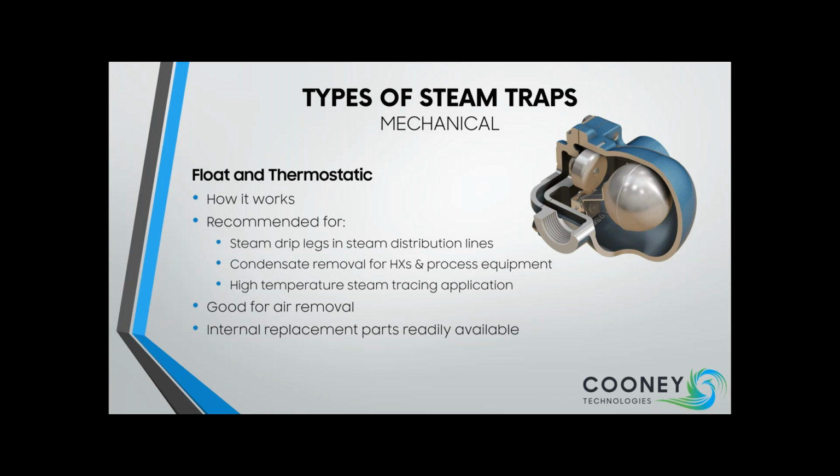We have the F&T trap, or the floating thermostatic, that has an internal mechanical hinge float device you can see in the cutaway here. When collected trapped condensate raises the float ball, which in turn opens the discharge port, the steam system pressure forces the condensate out through the discharge port. When the condensate level drops, the ball float drops, the discharge port closes, not allowing any loss of live steam. It's pure genius. Wish I invented that.